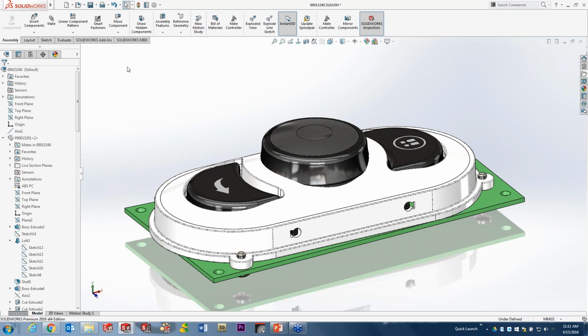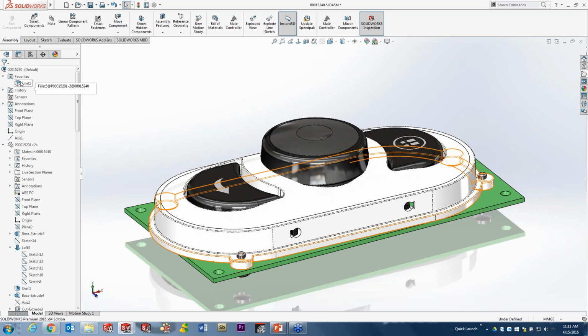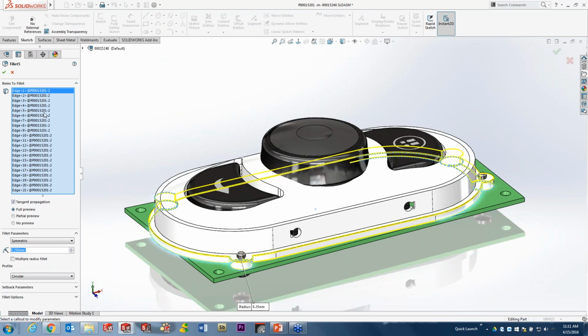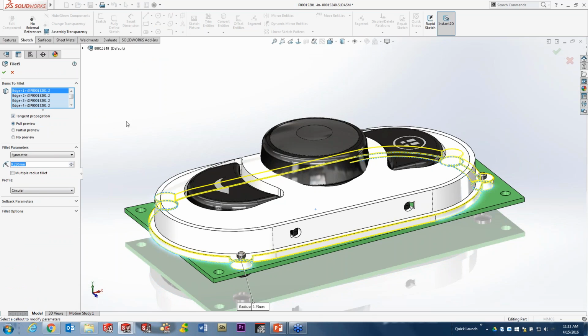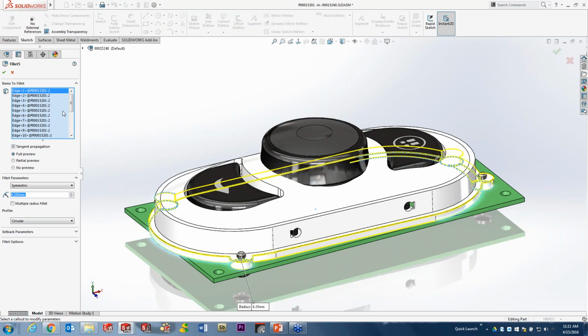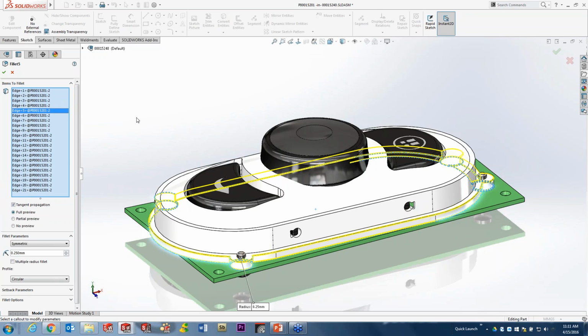The last thing I'm going to cover on this little demo set here is the selection tools. When you select a lot of entities in a feature, in SolidWorks 2015 and previous, this box would stay a fixed size. Well, here it automatically gets larger. In fact, this is what you'd see in 2015, which if you had selected 1,000 things, you can see them 4 at a time, but that's about it. Well, here this will not only allow you to change this, but if you double-click the scroll bar or if you right-click within this window, both of those will auto-size this. So as I expand that out, you'll get to see a complete comprehensive list of the selected entities for this feature.